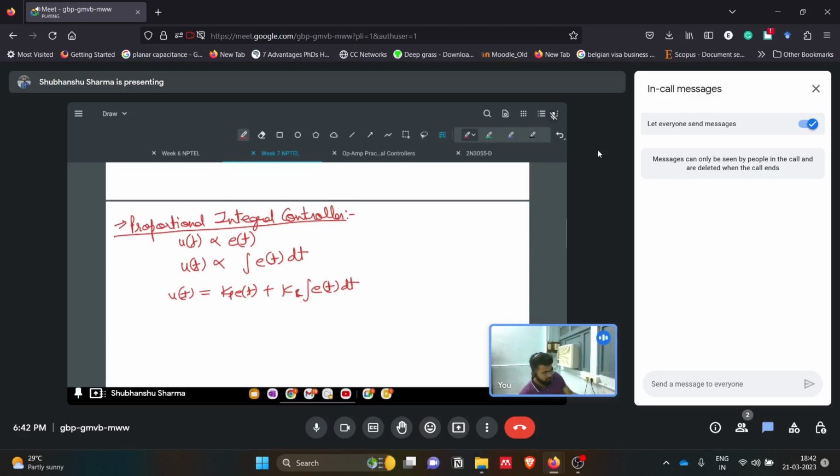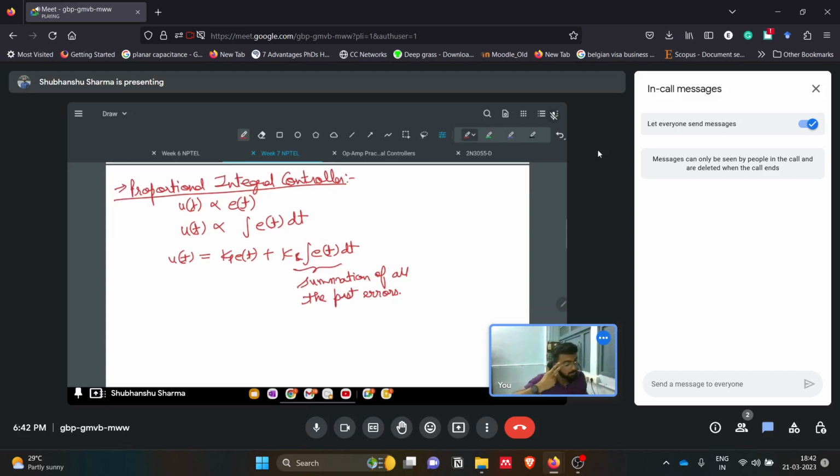So what is this? Basically, it is the summation of all the past errors. So not only the present error is being kept in mind, but also the history of the past errors is being kept in mind.